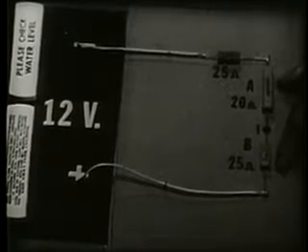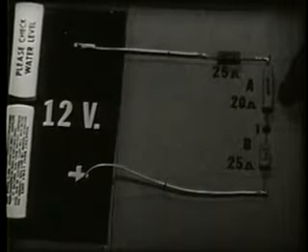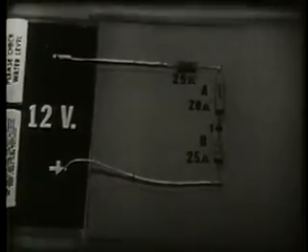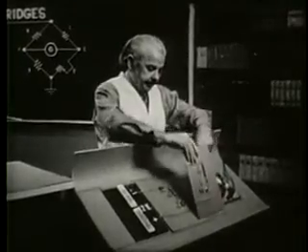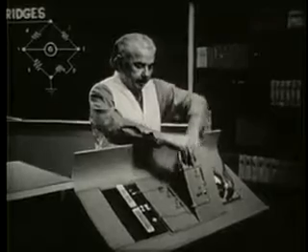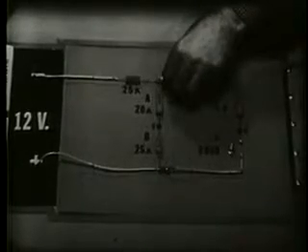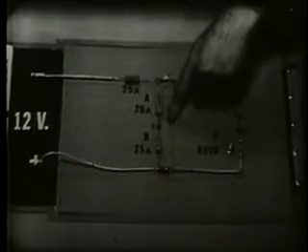You already know that a series circuit is a voltage divider. The voltage is distributed according to the ohmic value of the resistors. Now I'm going to take a similar series circuit and connect it in parallel with this one. Now we have two series circuits in parallel with each other. Each circuit is a parallel branch. Let's measure the voltages.